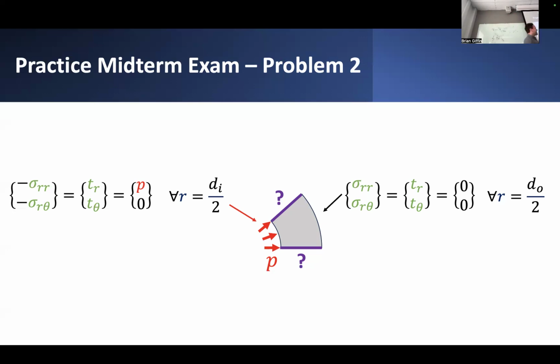So if we're not specifying radial displacement, we have to specify the component of traction that acts in the radial direction on that surface. In particular, we have to specify this component of shear traction along this surface. But of course, if there's nothing constraining these points from sliding along the symmetry plane, it's equivalent to saying that there is no shear traction on that interface that would otherwise prevent these points from sliding outward.